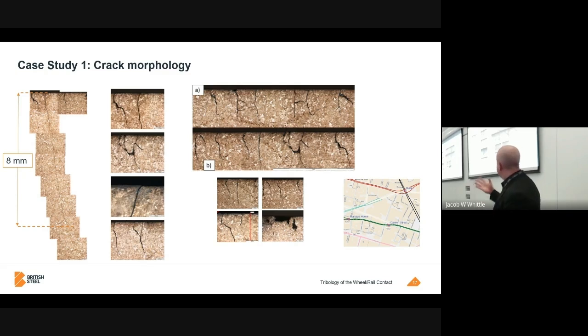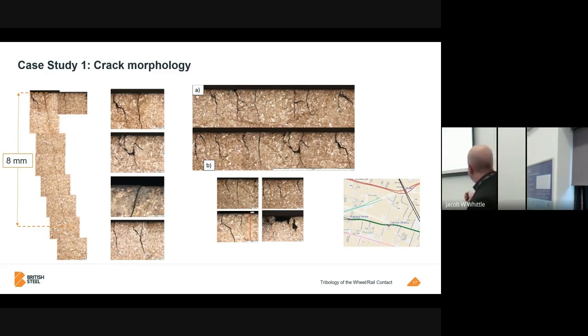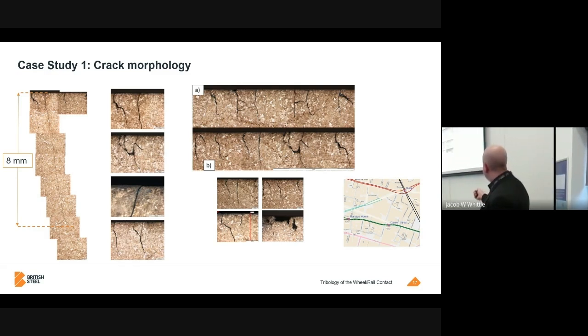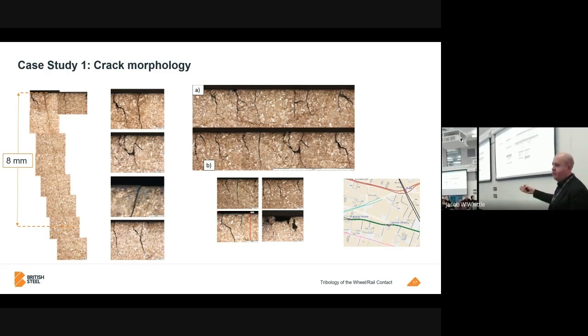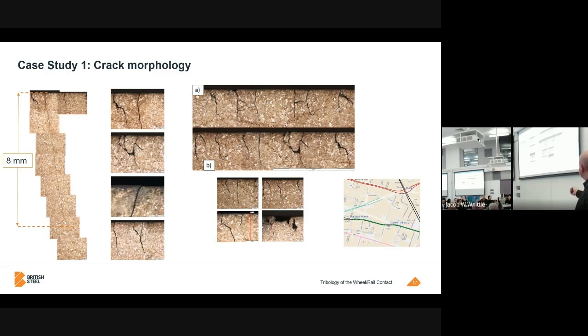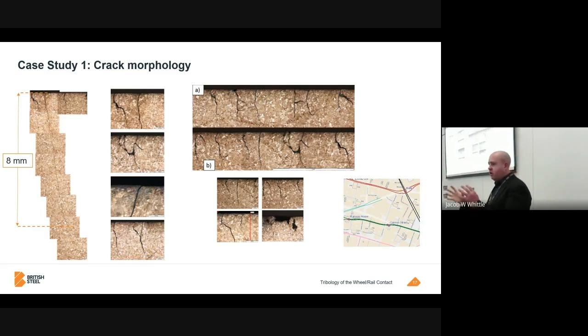And the other problem they've got at London Underground is automatic train operation mimics that behaviour as well. They've either got an on-off switch, it's either full throttle or full brake. And you end up with this very unique situation where, when the train sets off from here, the front end of the train will be accelerating around this curve, but the back end of the train is braking around the same curve as it comes into the next station. So you get some very complicated forces going on in the wheel-rail contact in this location.